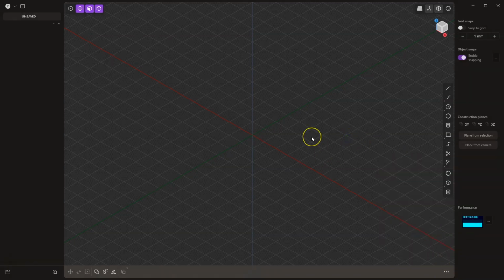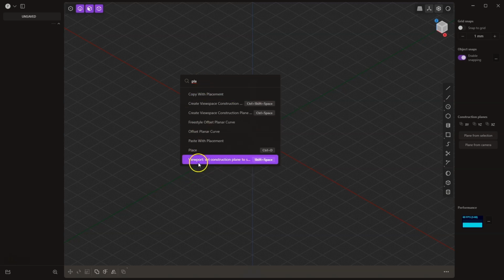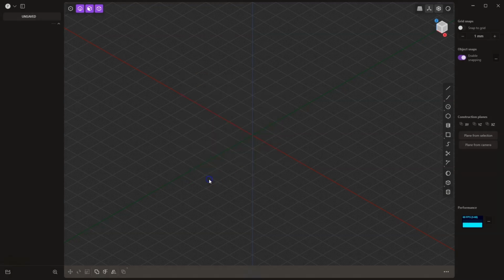As for this list of commands, we can activate it by pressing the F key on the keyboard. Then, wherever the cursor is, a list of commands will appear. From this list of commands, we can select a command. We can also enter the name of a command here, and based on that name, select that command. This may seem like a rather strange solution, but it is really very convenient. When I started working with Plasticity, many things could be done very quickly. This program really allows for quick creation of 3D models.